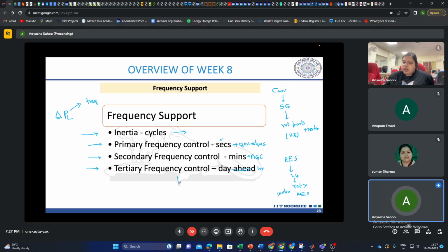So we know we are having some spinning reserve in our system, right? What is spinning reserve basically? This means the generators are on, because we know generators require some startup time. So generators are on and they are reserving their power for any disturbance. They are not producing it, so that when any disturbance happens, they do not have to wait for the generators to start again.